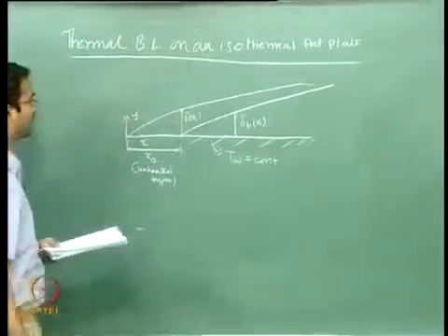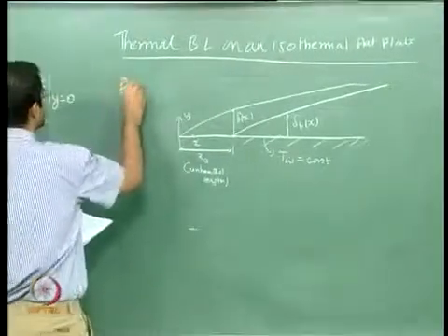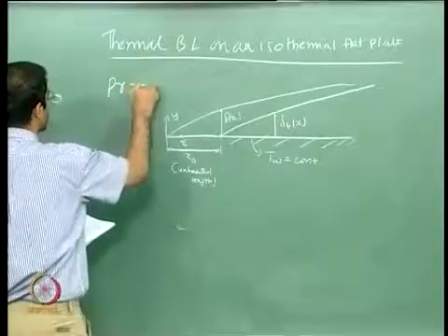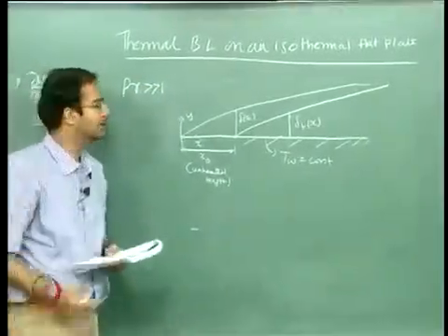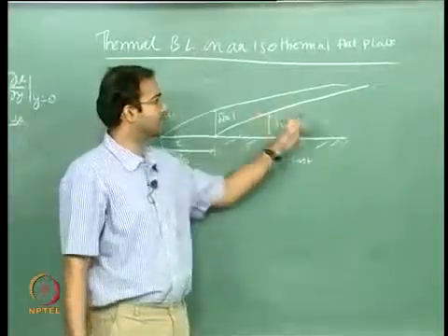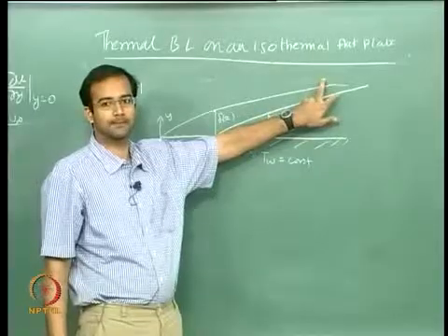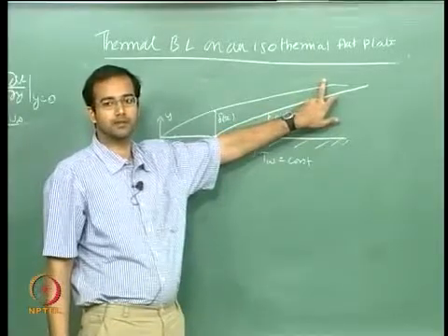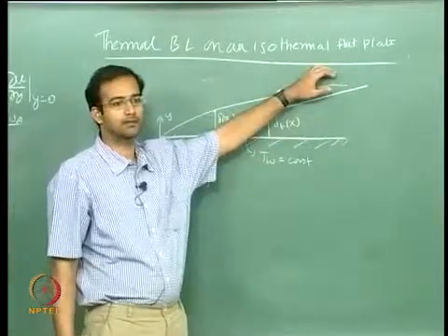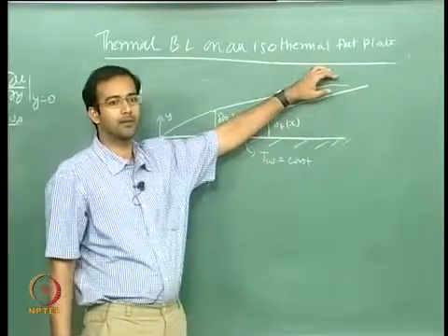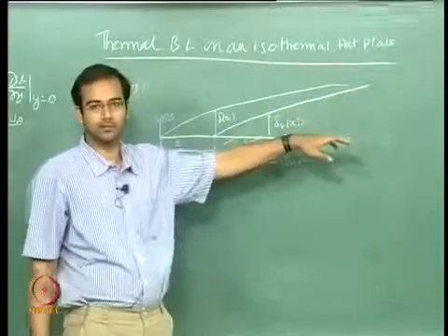Okay, so depending on the case, whether your Prandtl number is much greater than 1, approximately 1, or much lesser than 1, once it starts growing, the thermal boundary layer may overtake the momentum boundary layer thickness. If your Prandtl number is much greater than 1, then the thermal boundary layer thickness will be lower than the momentum boundary layer thickness. The momentum boundary layer thickness will be growing at a much faster pace, so the thermal one will not be able to catch up.